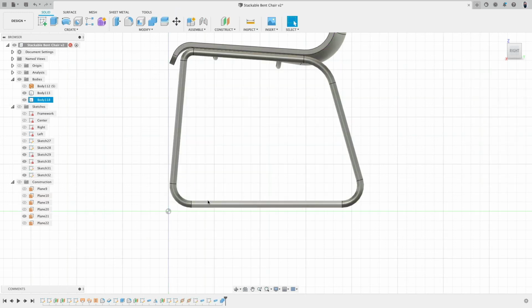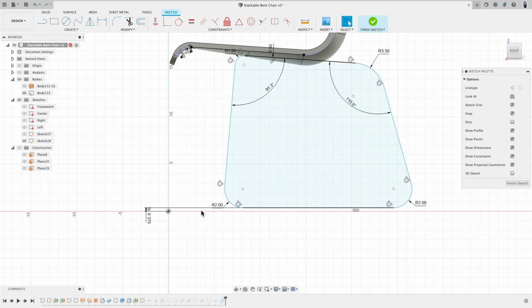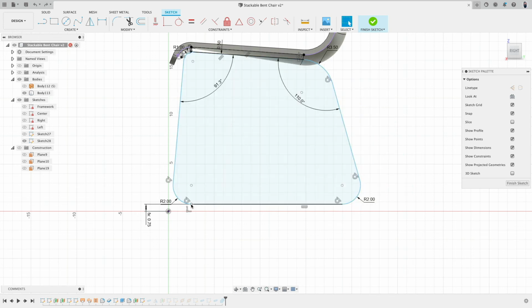Click OK. When you see, whoa, there's this gap. Why is this happening? Well, we made this distance the full size of the pipe. This actually has to be half of it. And then this jumps again. This is hilarious. So how do we prevent this jumping?